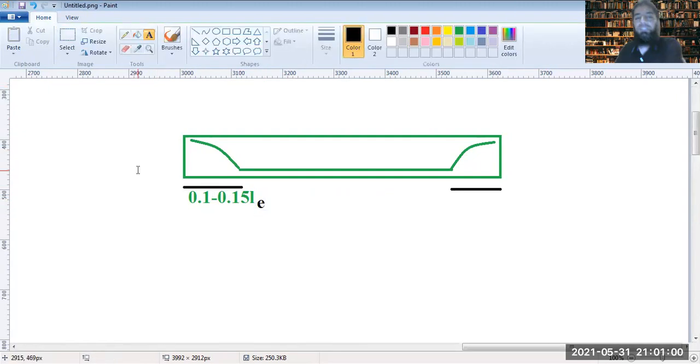That's the effective length. So thereby, the reason for cranking up of the bars, as I just mentioned, is that there is a certain amount of tensile force developing because of a certain amount of fixity, even when it's simply supported, because it's prevented from uplifting. There could be another wall over it, there could be something else over it. So there is a certain amount of fixity always in the slab. So thereby we are providing such a phenomenon. So that's about this lecture. Thank you.